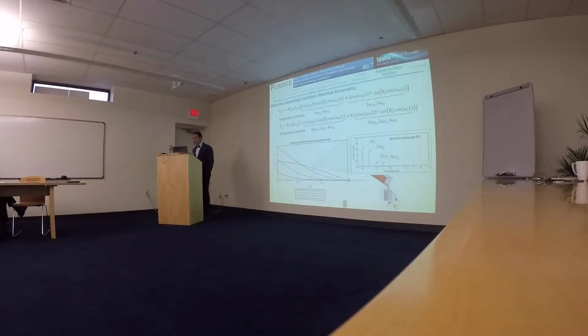So now the question is, can we use this information? And I would say the answer is of course yes, but which one? As we can see here, 3 and 4 times the payload oscillation frequency are very small, so they are difficult to use for a feedback. And now, the two oscillations at 1 and 2 omega 2, this is something we can use.